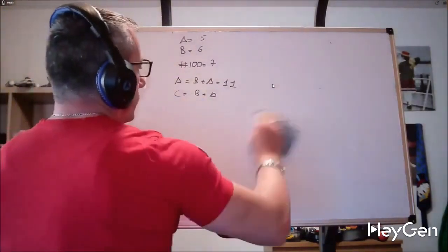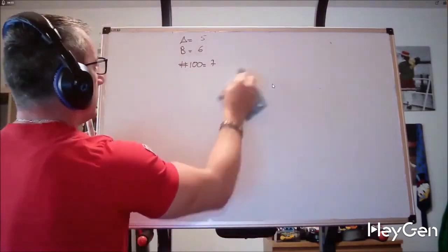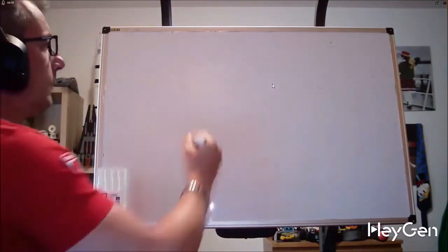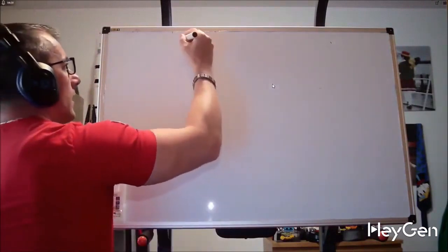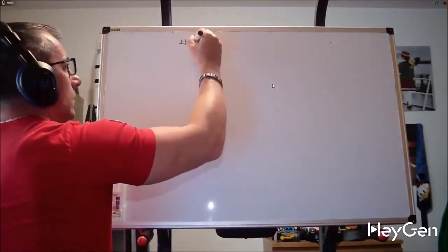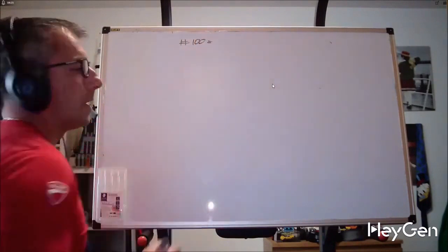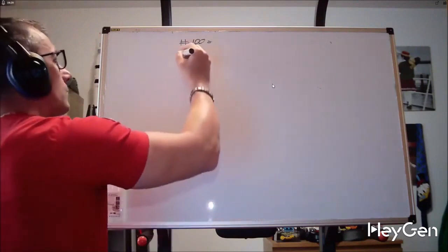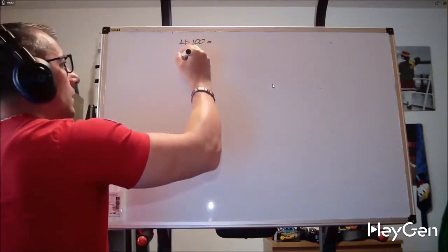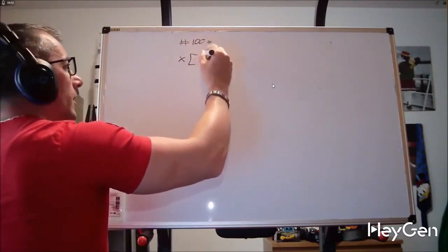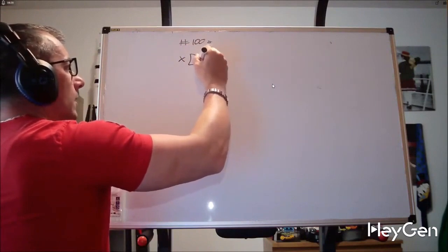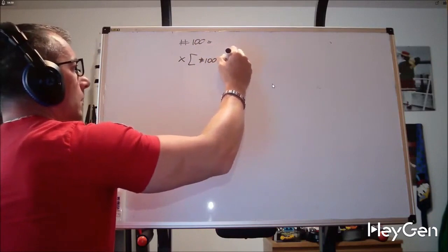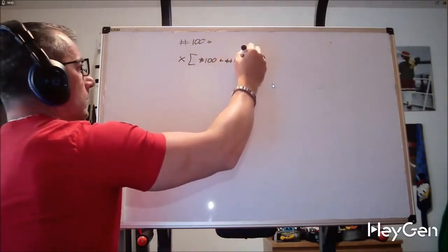So let's open a small parenthesis regarding our simulator, that is Fanuc. Fanuc identifies, as I told you, the variables with a hashtag, number, equal sign, and if I need to do calculations, x equals, open square bracket, #100 plus #101.